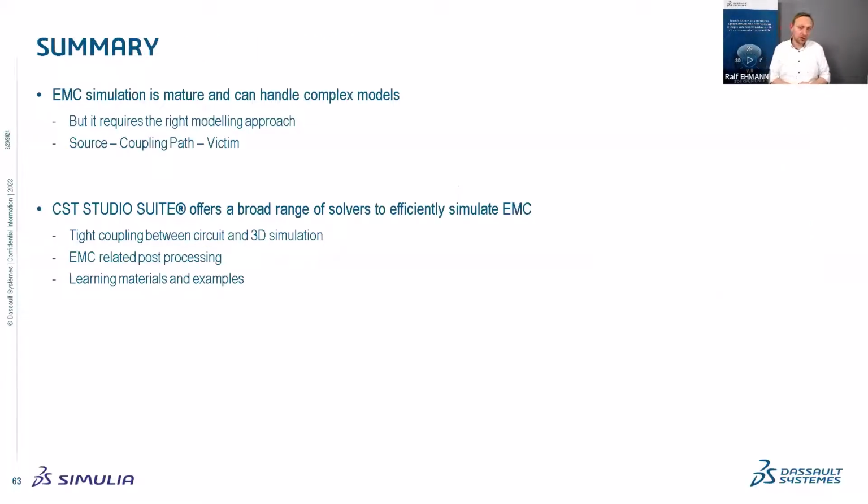I hope I could show you that EMC simulation is pretty mature and can handle complex models. It's not so simple. I have, let's say, medium complexity with the inverter, but of course there are possibilities to bring it even to very complex models, but it requires the right modeling approach. And then you start thinking in terms of EMC as a source, coupling path, victim, it helps you a lot to sort these different things out and understanding why certain things are modeled the way we are proposing.